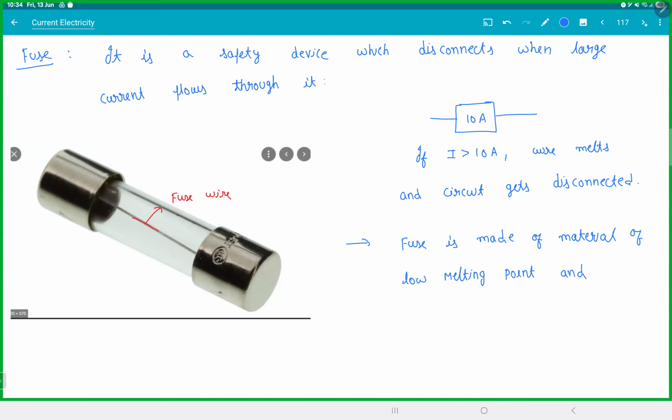That means the higher the specific heat capacity, the more difficult it is to change the temperature. So ask yourself, do you want the fuse wire temperature to rise fast or rise slowly? You want it to rise fast so that it can reach the melting point fast and melt. So you need low specific heat capacity. With low specific heat capacity, the temperature will rise even for small heat. Clear with this? So you can frame theoretical equations of that sort. Got this?